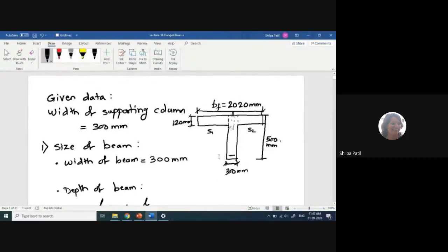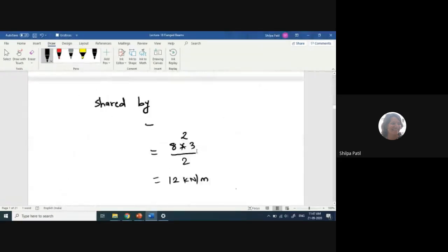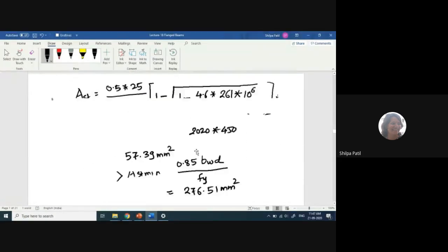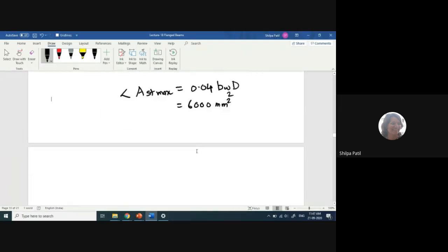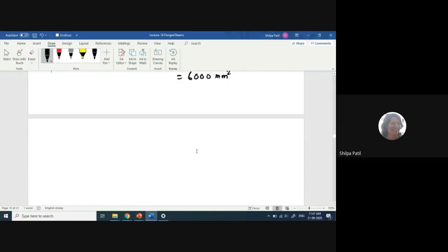So instead of that, if the area of the steel coming is higher, not say 500, 600, but if it is coming 1000, go and increase the diameter of the bar. So that our problem of providing the reinforcing bars in 2 layers or 3 layers will be eliminated, and we will be able to provide the bars in one layer only, in one row only, which will satisfy the check for width also.